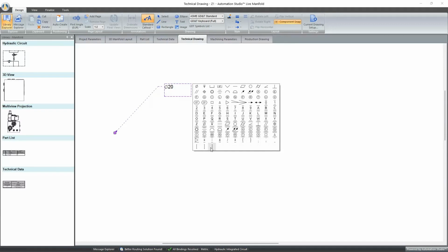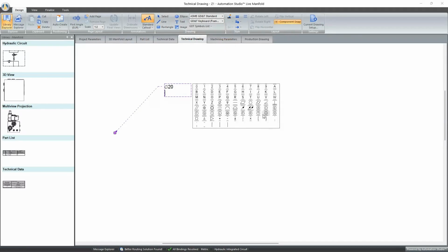I have the separators. So if I want to add a specific, for example, geometric dimensioning, I can add a frame. I can even make it easier for myself and add the frames here. I can select geometric tolerancing, add a diameter. We can make it imperial even. I can put 0.25.